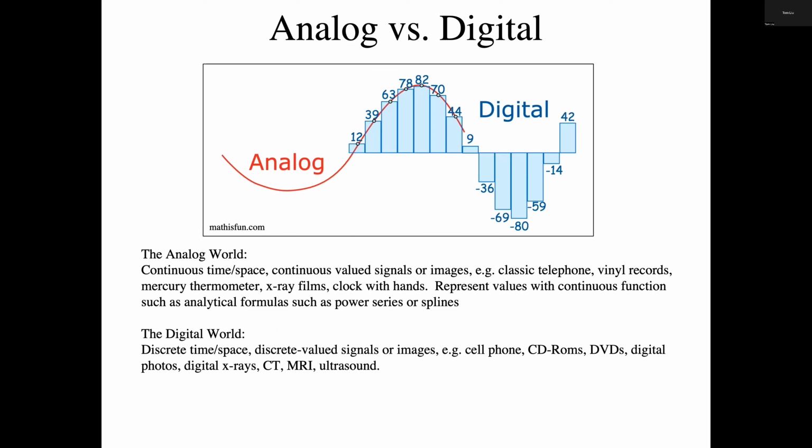So, this is the boundary between the digital world and the analog world. Our functions that we're measuring usually are analog functions, essentially. So in X-ray, if I shoot X-rays through a patient, and then right before my detector that's detecting the shadow that the patient's cast, you can assume that that shadow in space is a continuous function. You could sample it down to arbitrary resolution and it would never quantize itself.